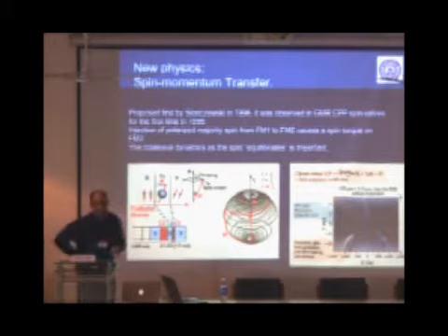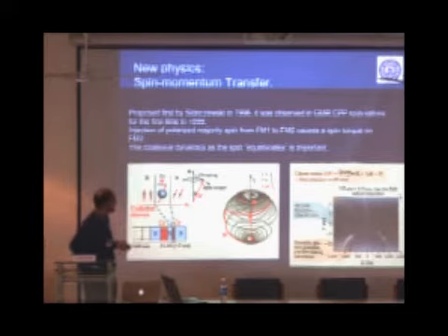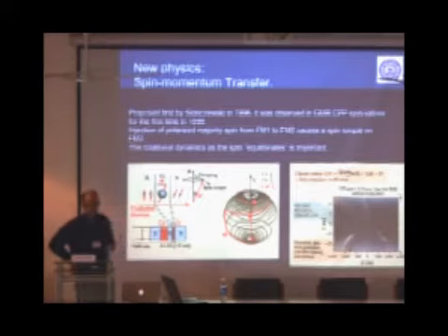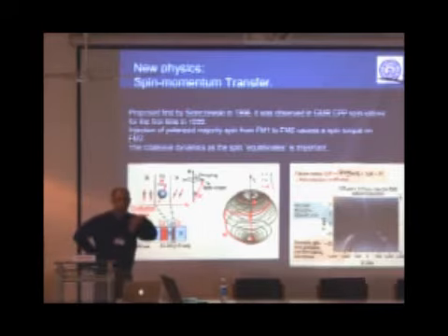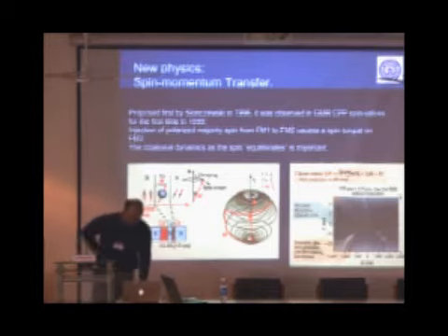It allows you to go really fast. You will be limited not by the inherent physics of the switching mechanism, as you are if you use charge-based storage in DRAM cells or SRAM cells. Here you will be mainly limited by the current drivers and other things. So the basic physics of how the storage works, whether you write or read it, doesn't limit you.